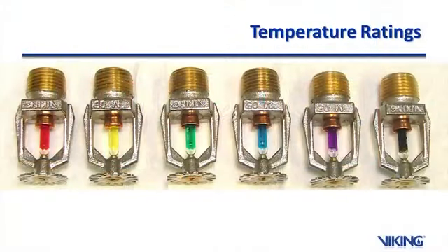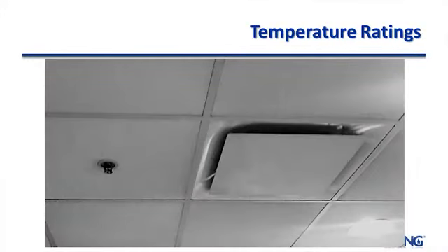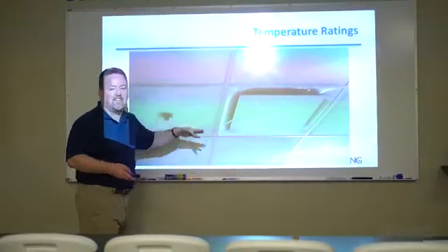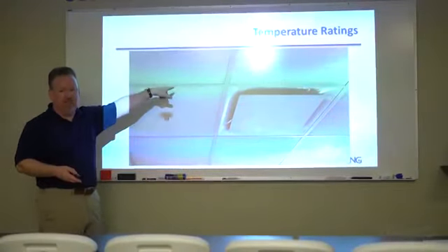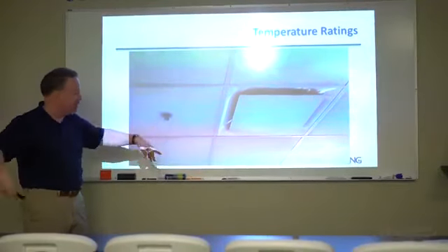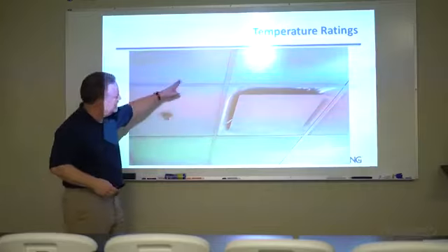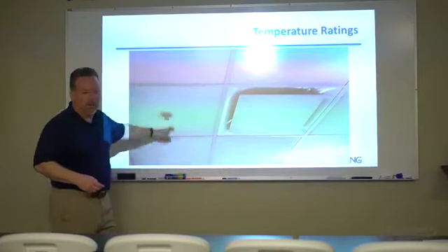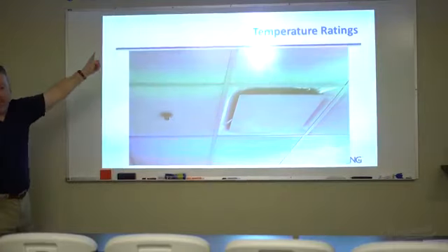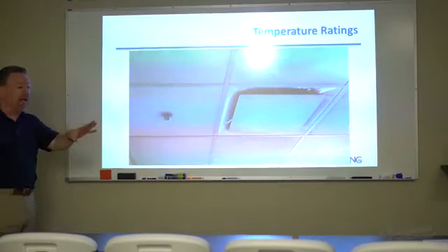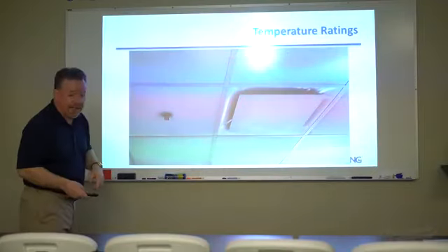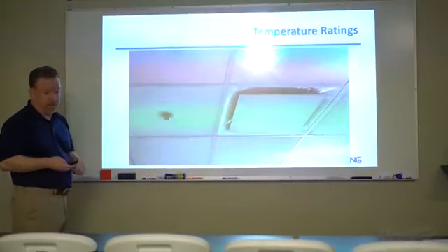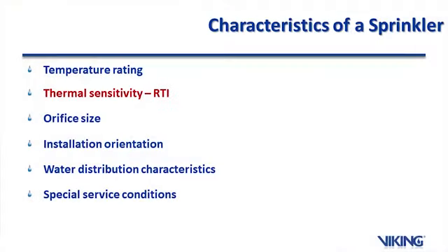Now that changes when it comes to ceiling diffusers. This is basically going to be a radius around this entire thing, and it doesn't extend as far out as the unit heater, because these just diffuse it out and it goes down. I want to be careful, but it's about a 2-foot radius around a diffuser like that. But again, NFPA 13 gives the designer that kind of detail to select the right sprinkler. So let's take a look at the second characteristic of a sprinkler.